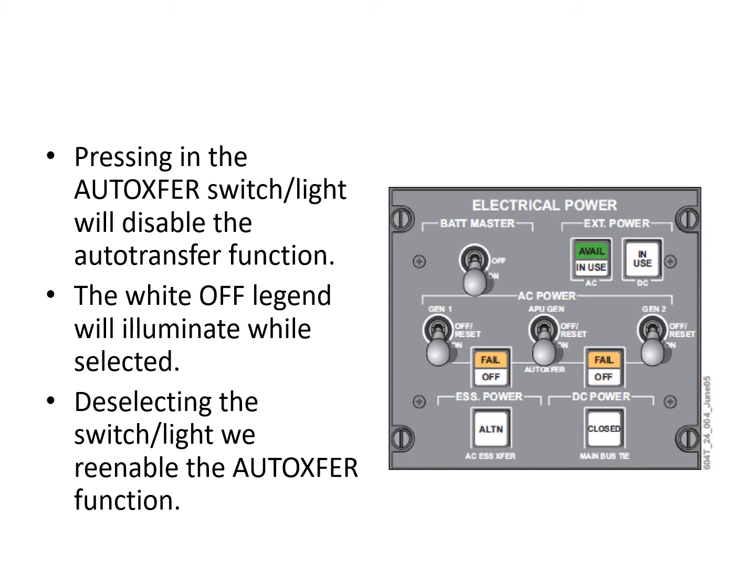Down underneath that you've got an essential power switch and a DC power switch. Looking at the essential power switch, if you remember, the essential bus is normally fed from AC bus 1, but it can take power from AC bus 2, and it will do so automatically. If AC bus 1 fails, there's a contactor, it just shunts across and connects it to AC bus 2. You can force that to happen for whatever reason you need to by pushing the alternate button, and now you'll force it to use the alternate source.